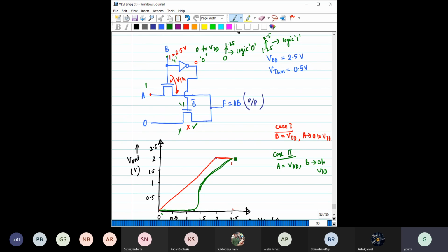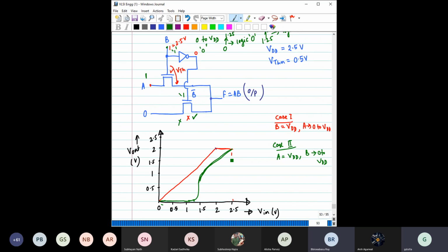So how does that affect? I think if we consider A to be the drain and F to be the source, then VDS is also changing. I mean, the VDS of the transistor will also change. So VTH of the transistor will also change. Very good point. Why do you think so? Sir, VDS, drain to source. Threshold voltage, right? No, sir, drain to source voltage. Oh, drain to source voltage. Okay. Drain to source voltage will also change. So I think it will shift from saturation to linear. That's why such changes occur.